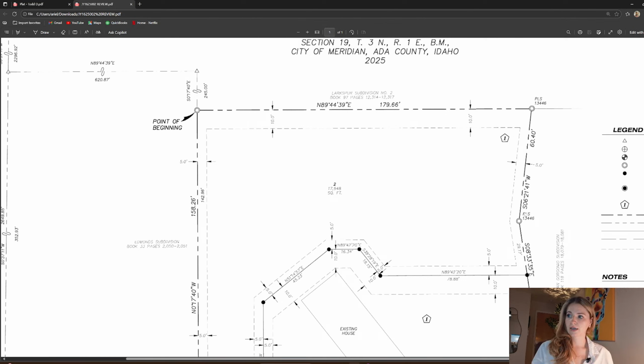So if we're looking at this one, that is saying if you're facing due south, so you'll be staring directly opposite of how you started. Facing due south, you're going to turn to your west, so it's still going to be turning to your right, and you are going to only turn 6 degrees this time, and then 21 minutes, and then 41 seconds. So it's not quite as dramatic of a turn. Remember, at the beginning, we were turning almost a full 90 degrees before we started walking.